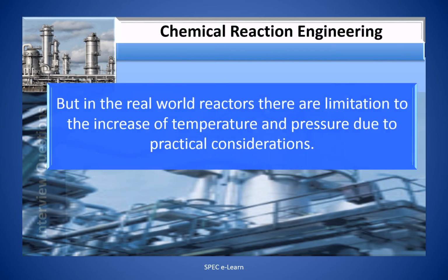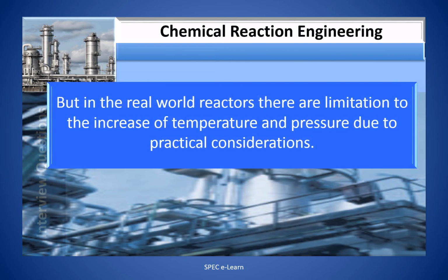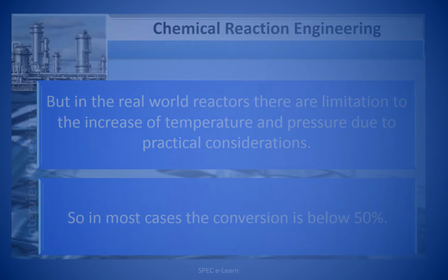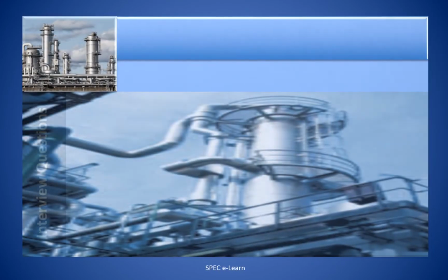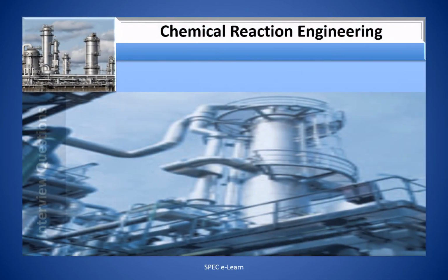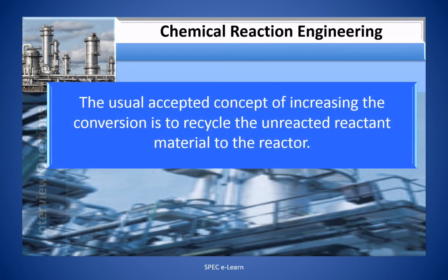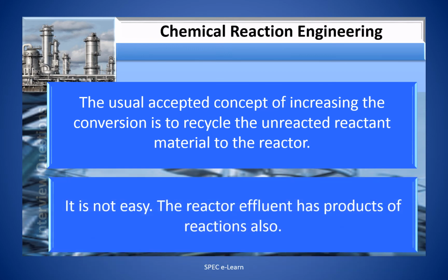But in real-world reactors, there are limitations to increase the temperature and pressure due to practical considerations. So in most cases, the conversion is below 50%. The usual accepted concept of increasing the conversion is to recycle the unreacted reactant material to the reactor.